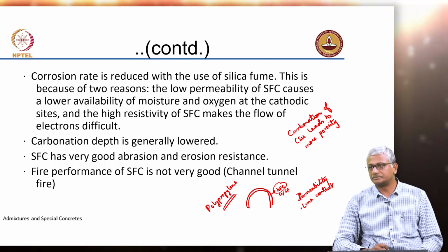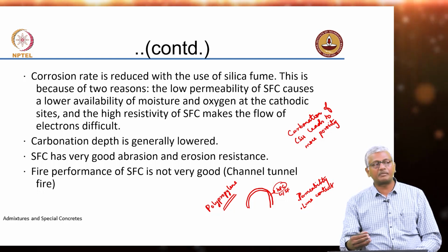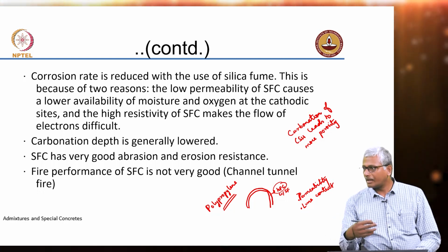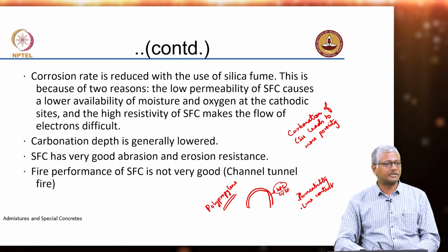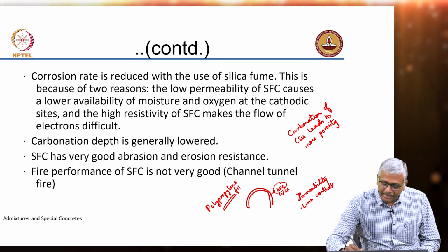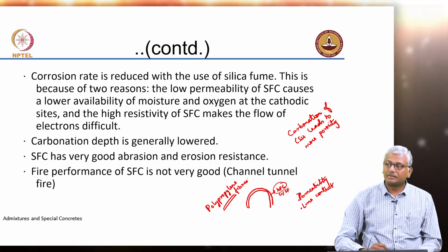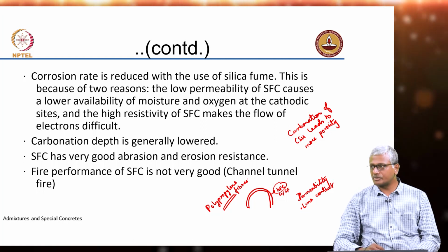Exactly. Pressure will decrease. So, at the temperatures of the fire, the polypropylene fibers start melting, and it allows the passage of steam to the external environment. So, polypropylene fibers as an additive to concrete used in tunnel linings is a very popular choice these days.